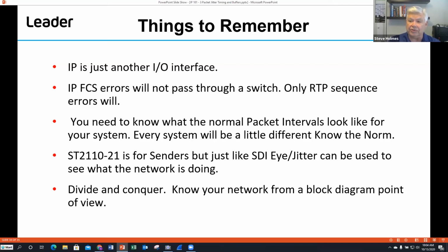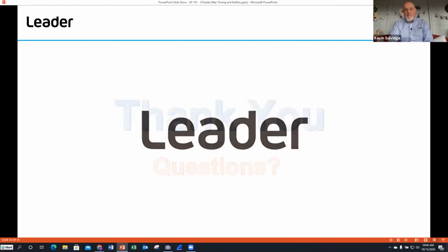And obviously the other advantage of that is that should you lose the GPS connection, because they're in the same device, they will stay locked together, and not that they'll drift hugely, but they will move together. And that's another issue that you can see if you have separate devices with black burst and PTP. You lose GPS and they deviate at different rates. So that when you transition from your IP world to your SDI world, you get an interruption to the